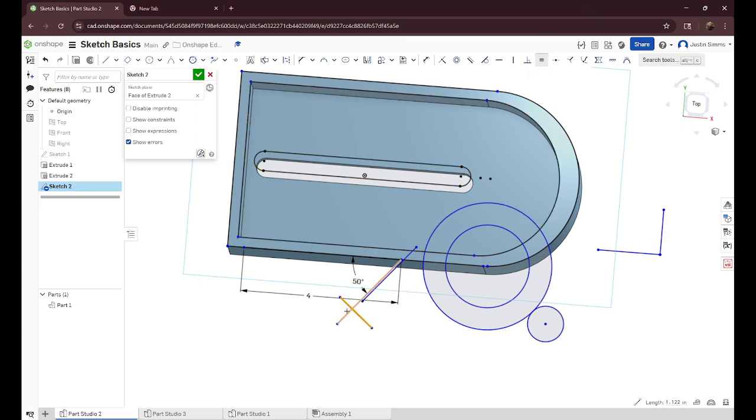The equals constraint makes two things have the same size. So like circles, you can even do curves and stuff. You can use the equals constraint on those as well. And then midpoint, put something at the middle point. So with an actual point, you could just make the point the middle point of a line, or you can make the end point of a line the middle point.